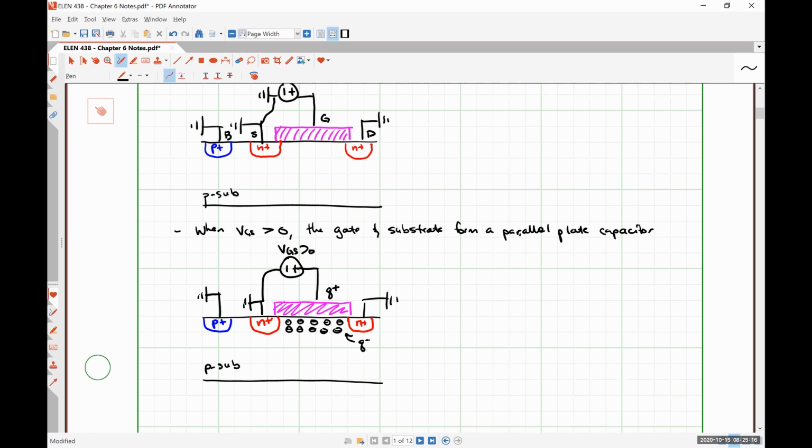So we have a positive charge stored in the polysilicon, and negative charge stored in that region between the two N+ implants, our source and our drain. And so we see a simple parallel plate capacitor. That'll be true as long as the source and the drain are at the same potential. Once we start screwing with the source and drain voltages, we'll see a couple of other phenomena.